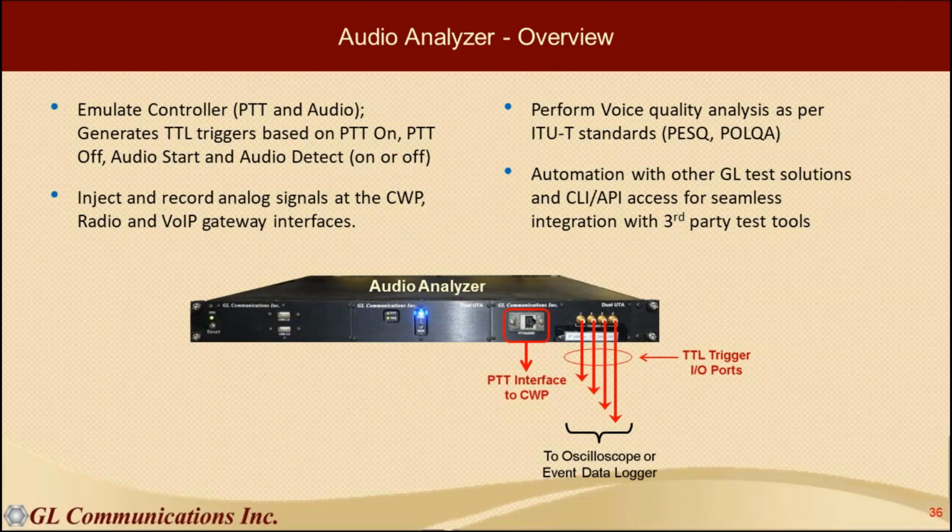It has the ability to send and record voice, as I mentioned. So it can do voice quality measurements from end to end, from different points in the network. We're using the latest telecom standards that are out there, which are PESQ and POLQA, to do that. We also have some IP standards, R-factor, E-model, and so forth, that we show. All of these products can be set up for automation, and we have CLIs and APIs available so that third-party tools can use them.